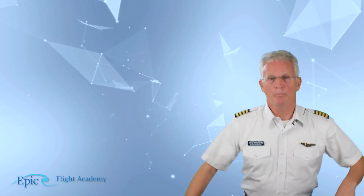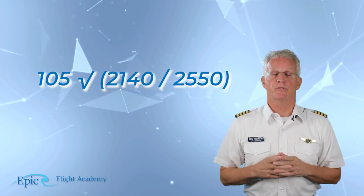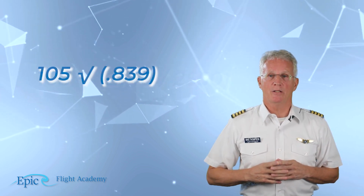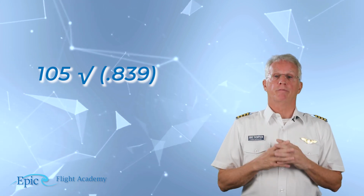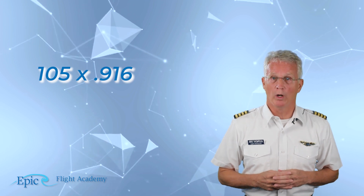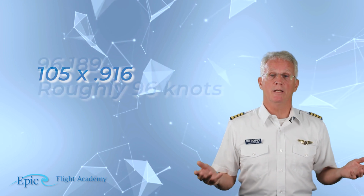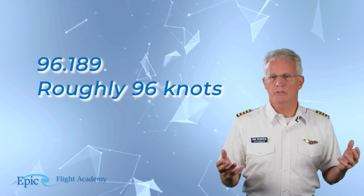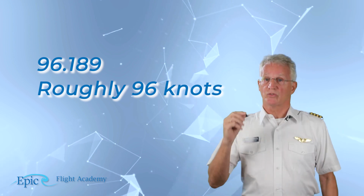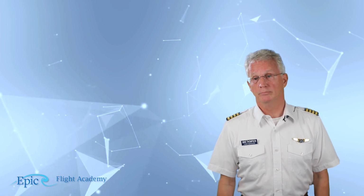And here we have it. 105 times the square root of that difference is 0.839, or 105 times 0.912. And the resulting answer is we get 96.189, or approximately 96 knots. This is our new lower VA speed.